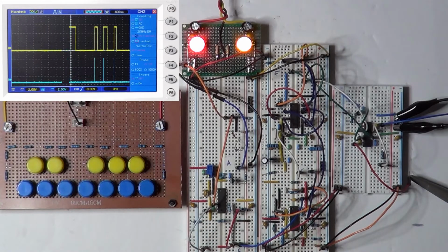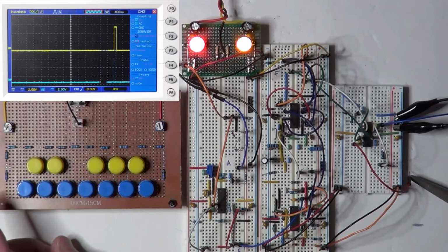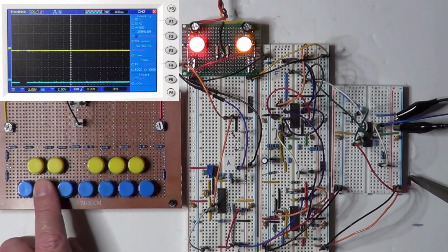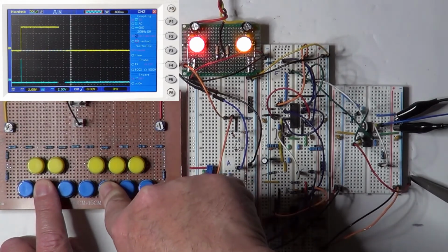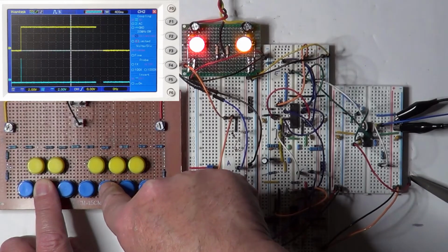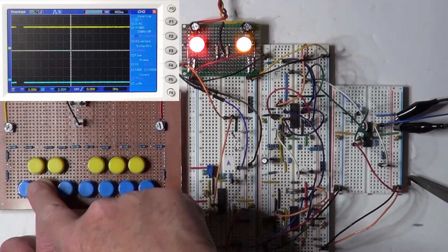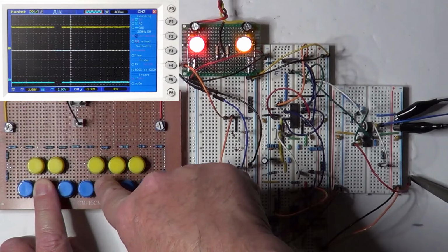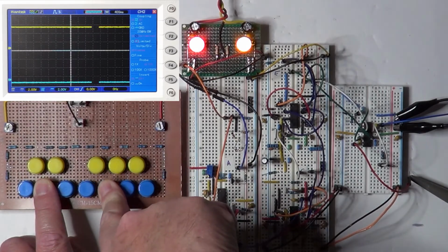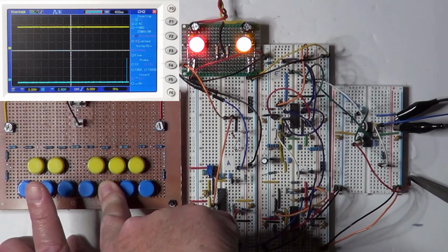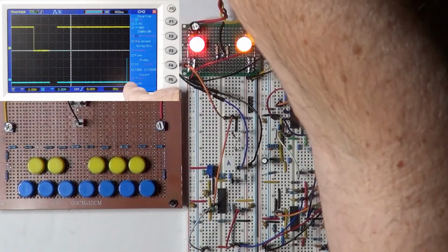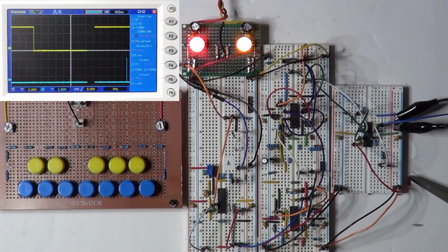And now let me show you what happens with multiple keys. If I press a lower key and then an upper key, see, this key doesn't do anything because this one, the one on the left, takes precedence. But if I keep pressing it and then I release the other one, here's the spike of the trigger for the new key, which means it has been selected. Only when I release all the keys, then the gate goes away.